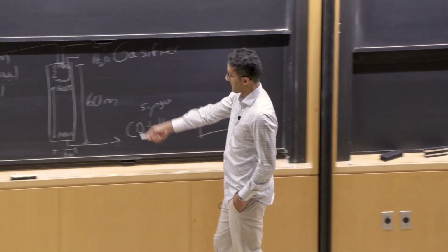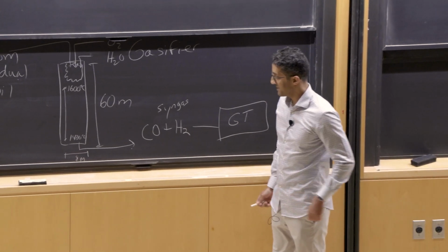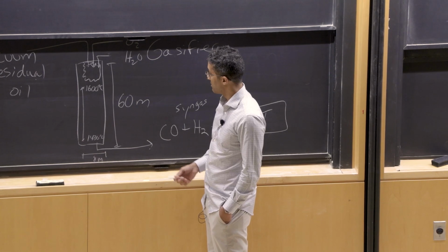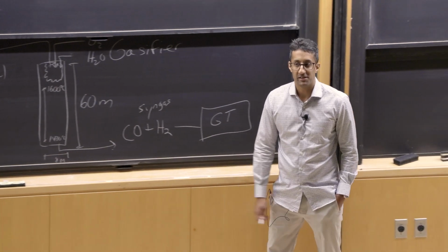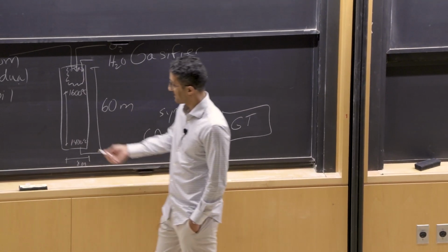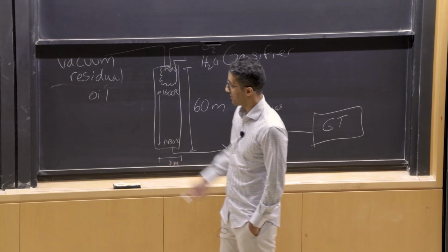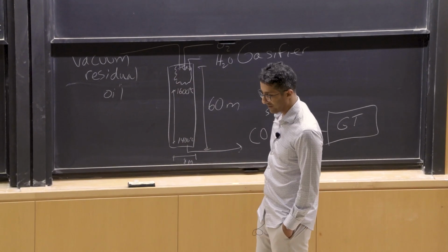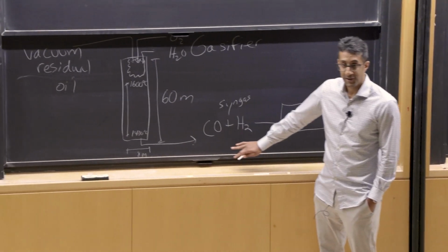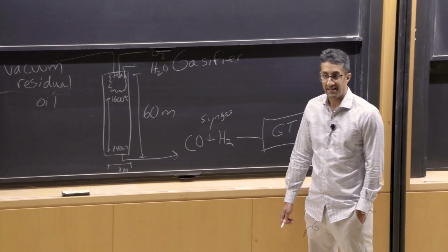Now this process, a 60-meter tall pipe, let's say, 8-meter diameter pipe, from 1600 C at the top to 1400 degrees C at the bottom, they wanted us to model the kinetics of this system. And first of all, this was extremely nasty stuff. So the R&D department of Shell made a project for 3 years. We developed kinetic models of this. We can predict the CO, the hydrogen, we can predict the soot, the methane. And then we gave it to the plant engineers.